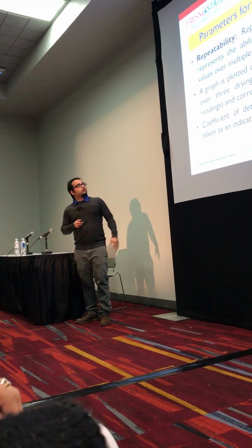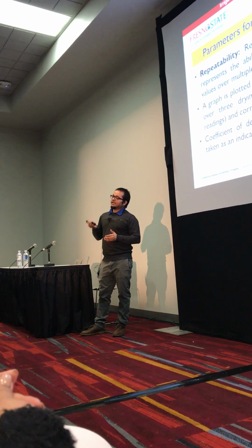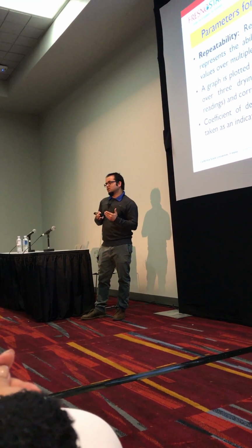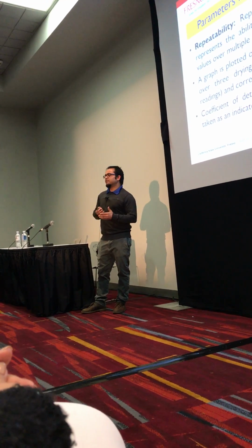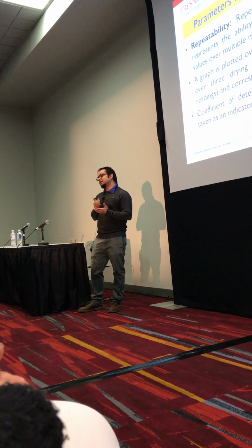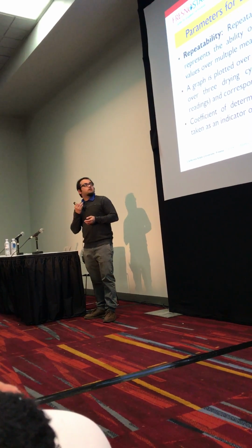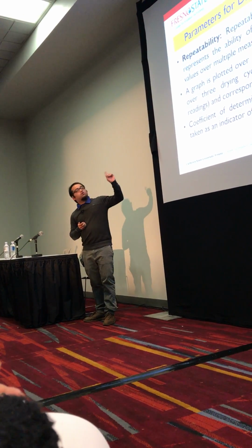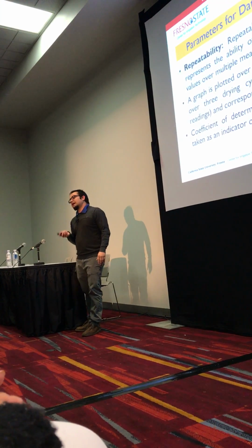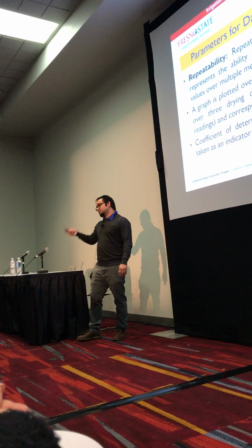Similarly, the second parameter was repeatability. We did the testing not for only one cycle, but for all 4 cycles, ignoring the first cycle, because when we prepared the soil by baking and grinding it, the soil structure gets disturbed. So we had to ignore the data from the first cycle. From the second, third and fourth cycles, we test the repeatability. That's why we introduce the term repeatability test, so that we can see how repeatable the sensor data are from the second, third to fourth one.